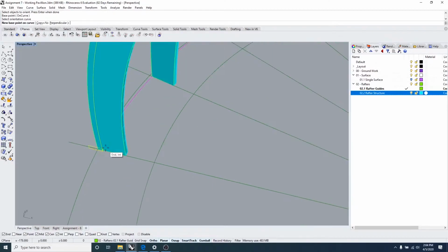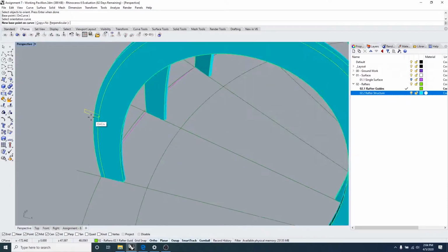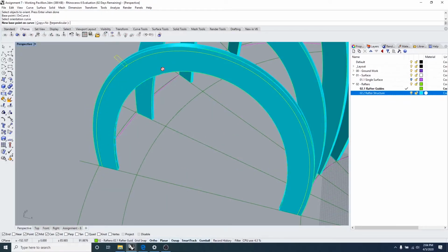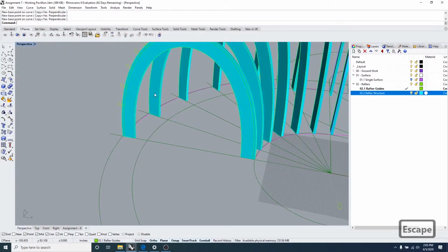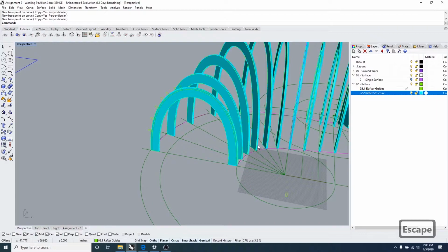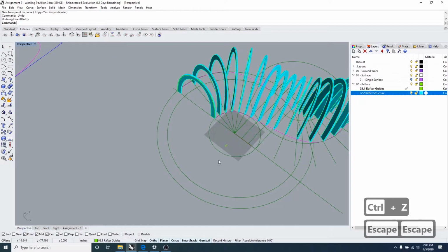And you're going to see that, yes, we have the curvature that is showing a preview along that curve. We can specify the copy in here on the sub menu just to have multiple instances in there. But it's on the wrong direction. It should be on the other side. So I'm going to undo one time and run the command again.